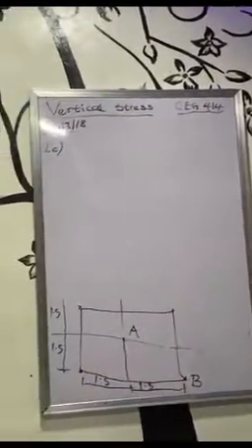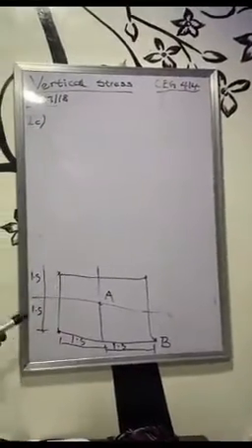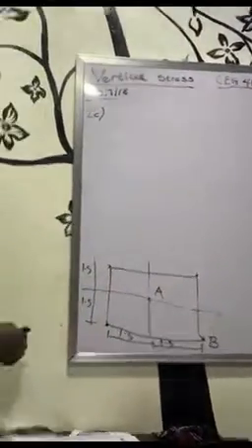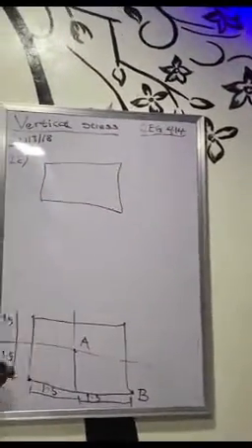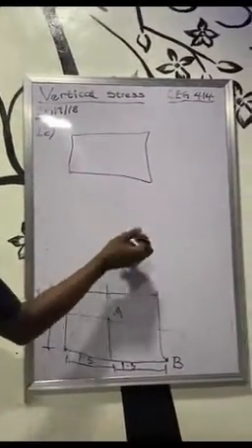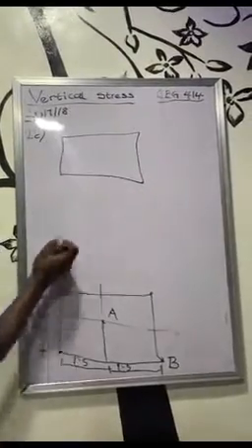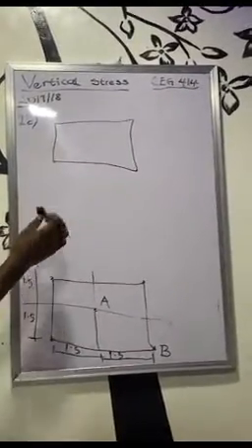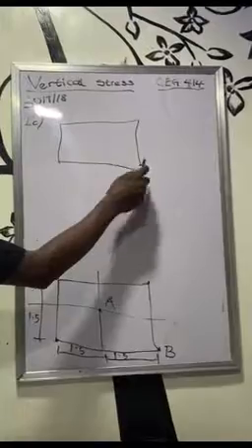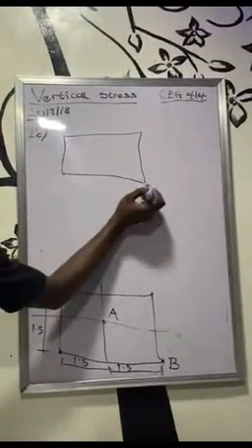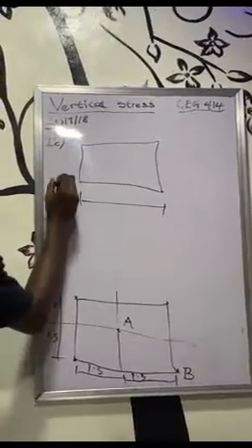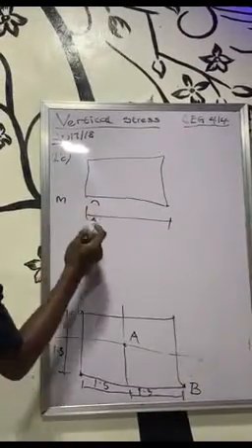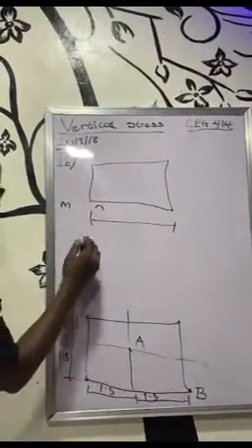When you are calculating vertical stress for a pressure acting on a rectangular or square footing, they usually break them up into triangles. So if you are taking vertical stress for, let's say, a square footing, at this point, I'll break it into a triangle. This is already a full triangle, and at the edge, I don't need to break it again. I'll just take vertical stress at this point and use this as, now we have something we call M, or we have something we call N. I'll use this for my N. Don't worry, all this makes sense later.